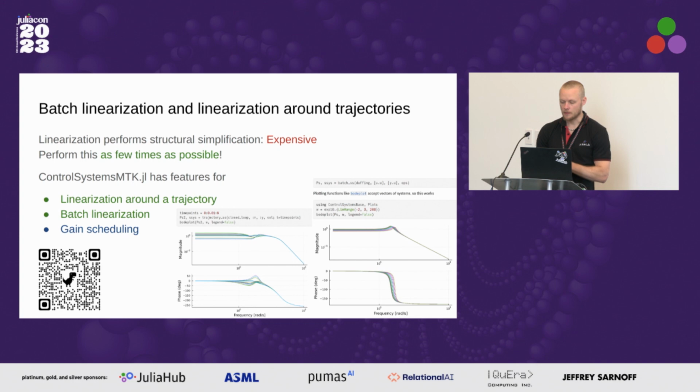What are some other things we might be interested in doing? Very often we want to analyze our nonlinear system in multiple different operating points. For instance, if we operate an aircraft, that is a nonlinear system, and the two most significant nonlinearities are related to the altitude and the forward velocity. So maybe we want to linearize this system in 10,000 different points in the forward velocity and altitude space.